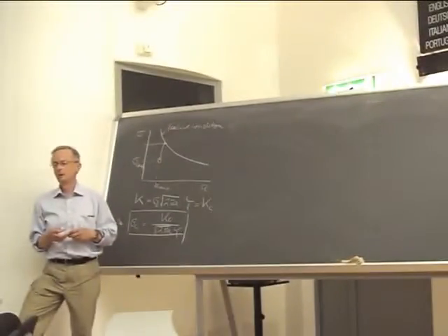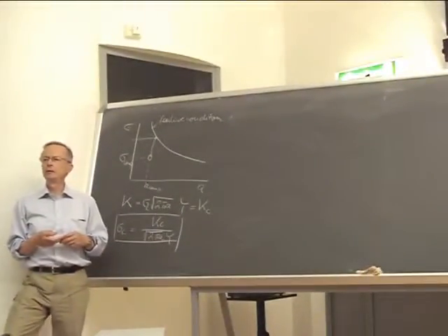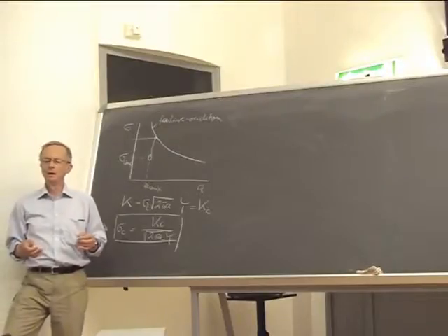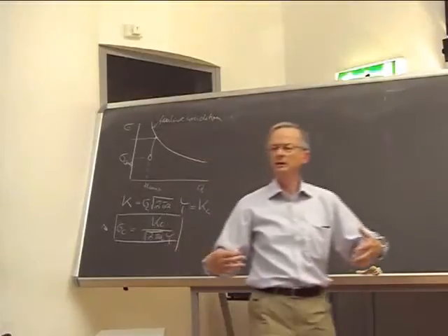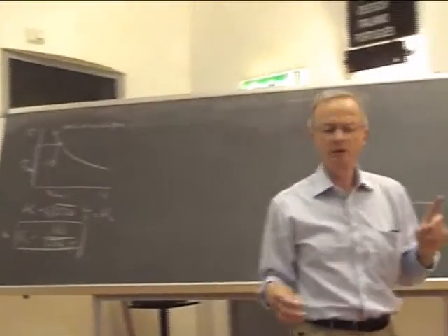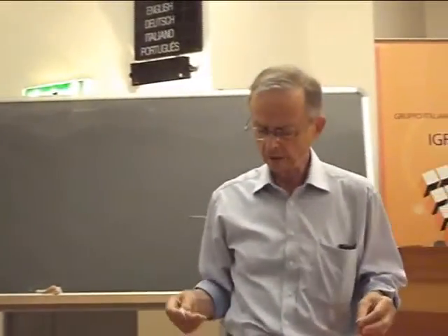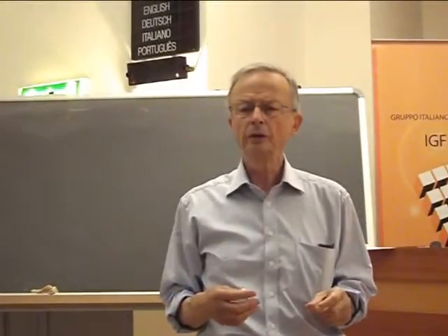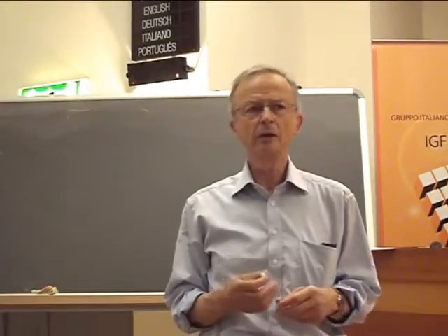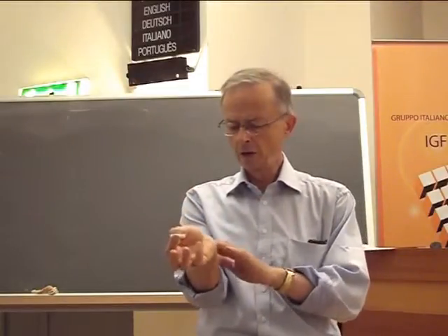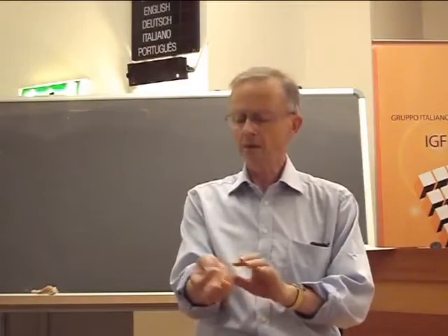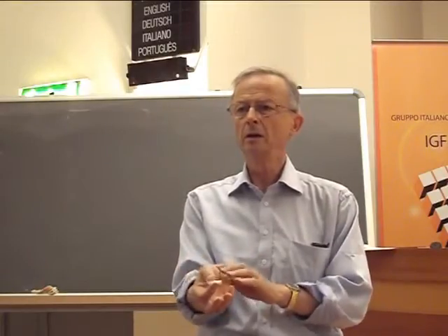Or you reduce the applied load. This can be done, for example, when you have a pressure vessel. You attach a steel belt, or whatever it is. And please, pressure vessels are not only thick-walled stationary structures. You also need pressurized components in aerospace structures, see rockets, you know, or the combustion chamber of an aeroplane turbine.